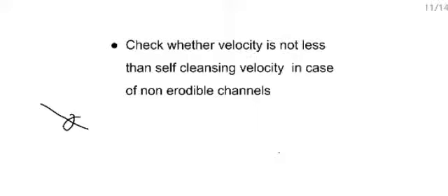So either you can use the Stokes settling velocity, the terminal velocity, that is the vertical velocity of the particle only. There you find, I think, in Stokes law, we have the vertical velocity of the particle, and the velocity of the particle should not be less than that value. Take care so that there is no deposition.